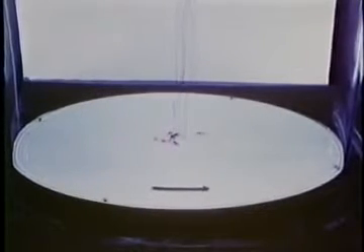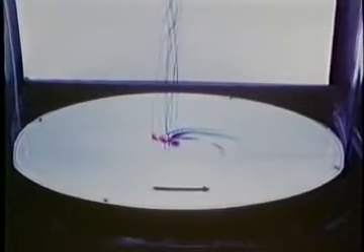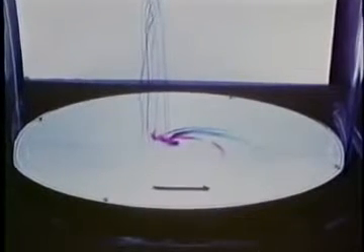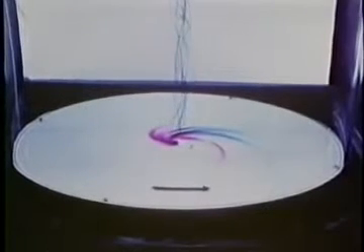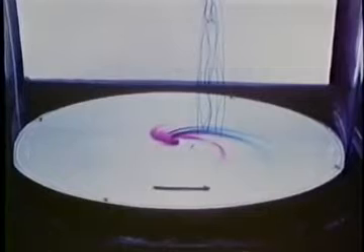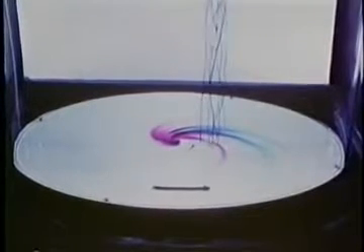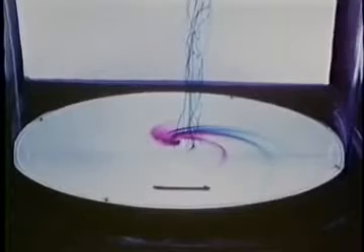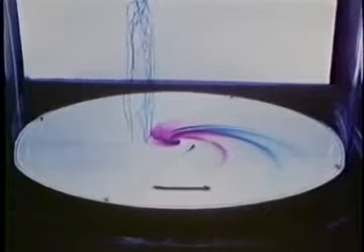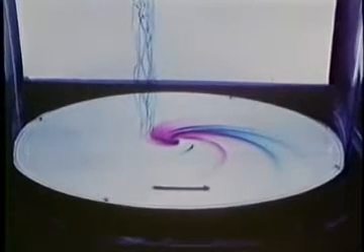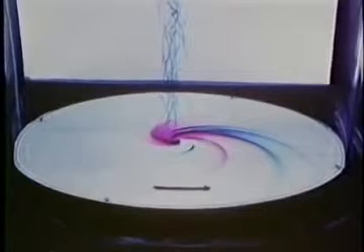Here, the tank and water were in rigid body rotation, and I have just increased the speed of the tank slightly. Dye tracers show that the main body of the fluid is rotating clockwise relative to the camera, while there is a strong outward flux in the viscous layer at the bottom. This is called an Ekman boundary layer. A vertical sinking motion in the fluid above is required to supply it. This flow in the inviscid region stretches the vortex tubes and increases their spin rate up to the new value much more rapidly than would otherwise be the case.